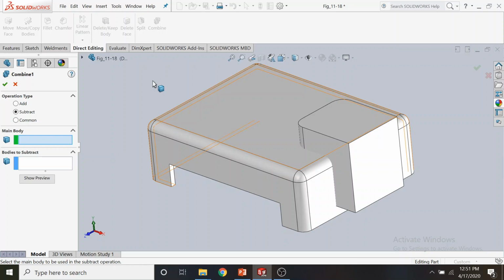But in Boolean operations, there is a small disadvantage. We cannot have a small gap between the main body and the tool body. So if you want to have a gap, you can't use the Boolean subtract operation. So we will see after this loads.